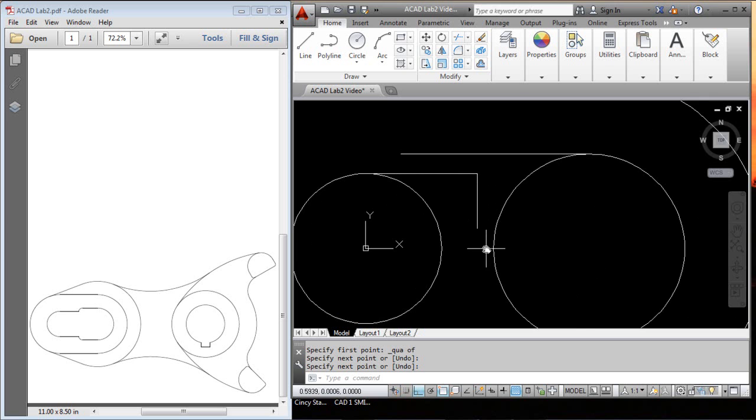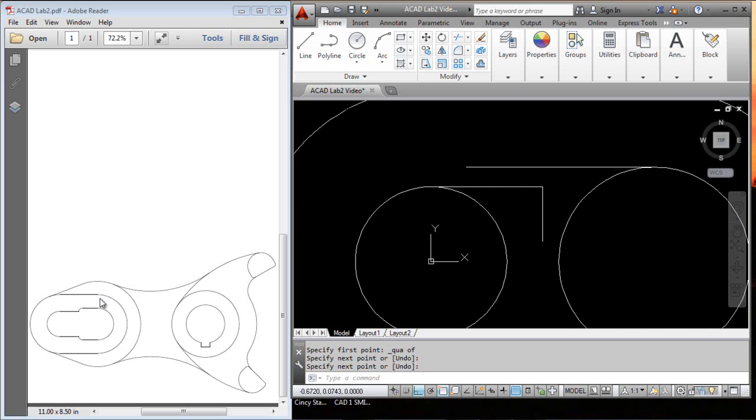So now the next thing I need to do is put a fillet in there. That's why I needed this vertical line. I can't put that fillet between these two horizontal lines. People try that all the time, and you can put a fillet in there and it'll make a slot, but it will not be right. It has to be between the vertical line and the horizontal line.